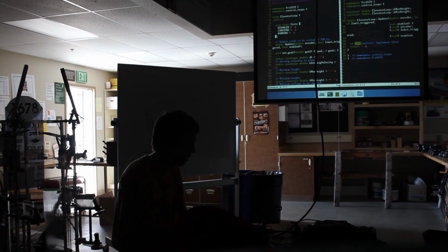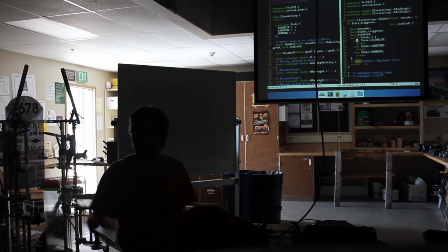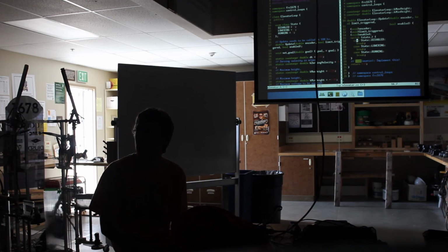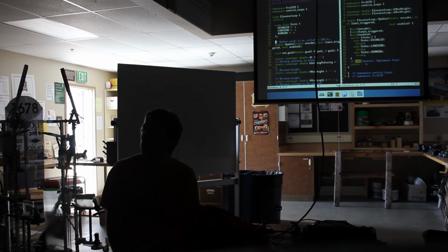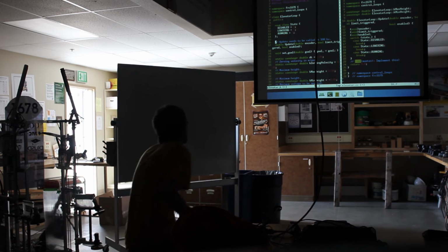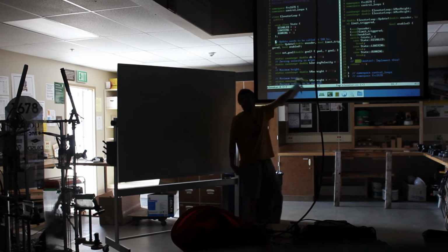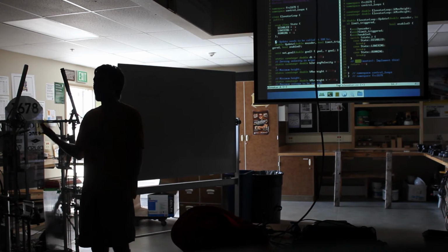Okay, so then we need a state variable. All right, so now we need to start filling these out. You could do a while statement, I guess. Yeah, a while statement while the Hall sensor is false. So what is the contract on the update function? What have we told our users that we're going to provide with this function? What we've said is our contract is we're going to require a user to call this at 100 hertz, and kind of implicit in that is we're going to return immediately. So if we put a while loop in there and wait, does that work? No, I see that.